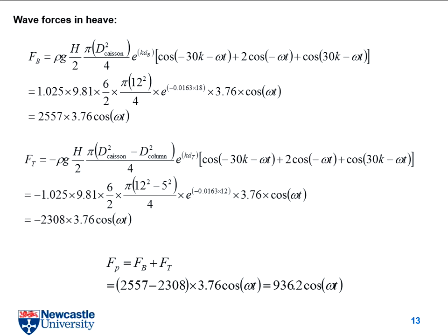From your formula table, we have an expression for your pressure, right? In the first page, the bottom one. You can see that we have two parts. The first one is rho gz or something. But please remember that this is static force. It will not give you response. That is just for your buoyancy. That is the stable part. But we have the dynamic part. That's the second term. This term will give you the response because it's always changing.